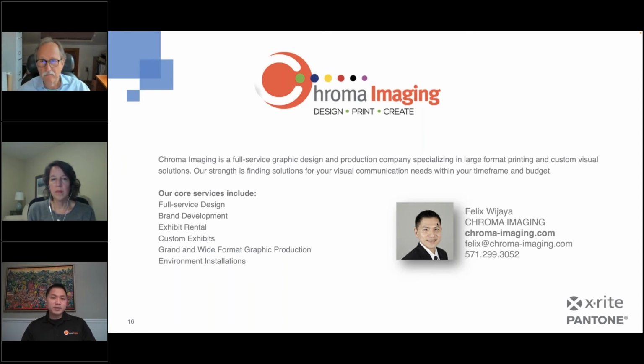the pixels, that's probably the easiest way to explain it. Different print heads can print different size pixels on different material. So you have to take a look at that when you do your color profile and color management, especially when you have 2 different locations. So we typically start from one location first, do all of the color profiles for all the different substrates, and they all will match within a tolerance.